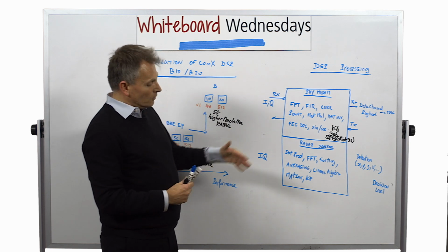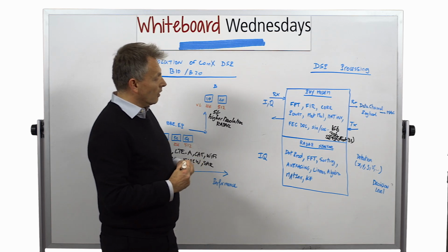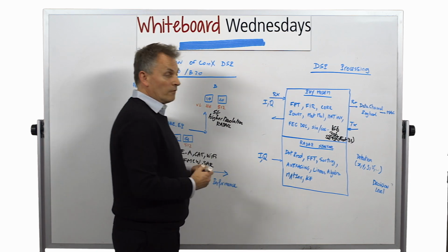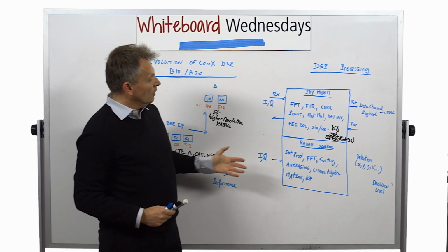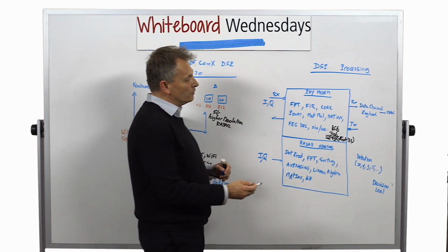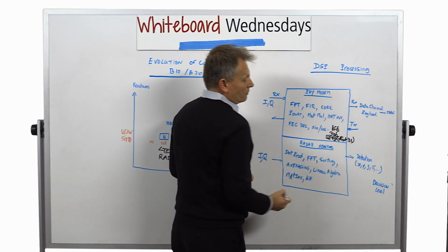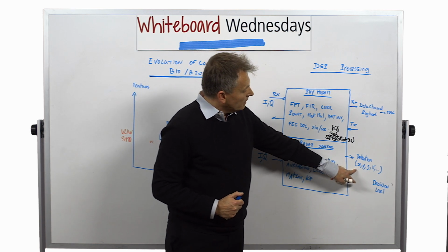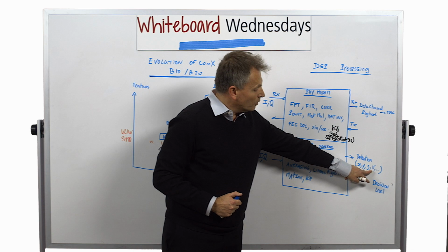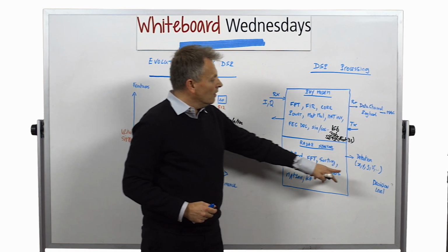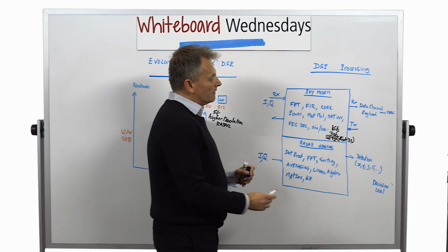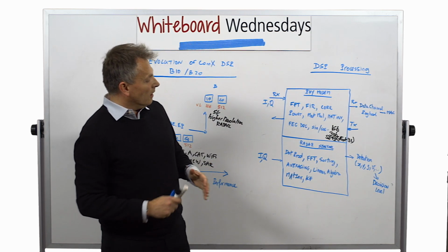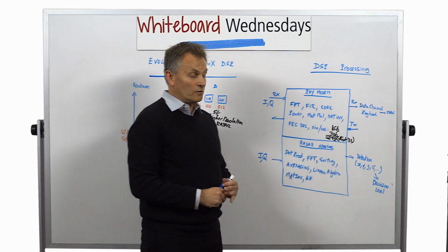In the case of the radar sensor application, we also have IQ samples from the RF interface going into the radar sensor. And the outputs are typically detections with different coordinates in space, x, y, z, but also velocity and potentially other types of characteristics. And this goes eventually into a decision layer, where various decisions are made based on the detection.